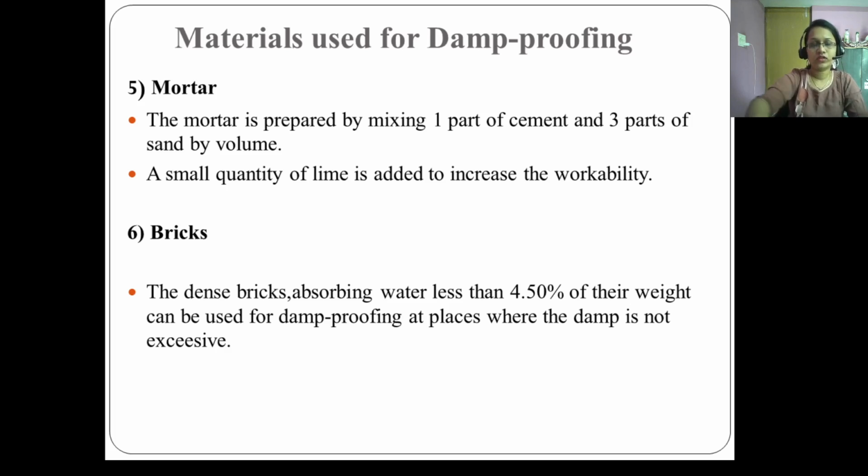Then we have the bricks. The dense bricks absorbing water less than 4.5% of their weight can be used for the damp proofing at places where the damp is not excessive.